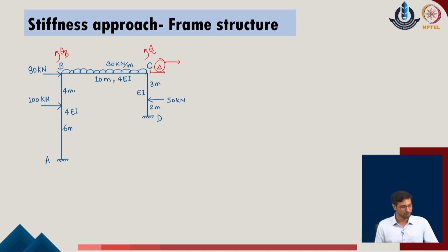So, to start with this part, we identify first the given system with respect to the same condition that all the degrees of freedom are restrained in the given problem. So, as we have initially defined, we restrain both of these supports of the given problem. As we restrain the given supports, we understand that corresponding to the given loads which have been identified in the given problem, we can now calculate the end reactions of the given system.